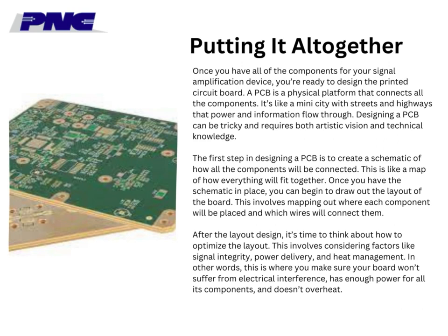The first step in designing a PCB is to create a schematic of how all the components will be connected. This is like a map of how everything will fit together. Once you have the schematic in place, you can begin to draw out the layout of the board. This involves mapping out where each component will be placed and which wires will connect them.